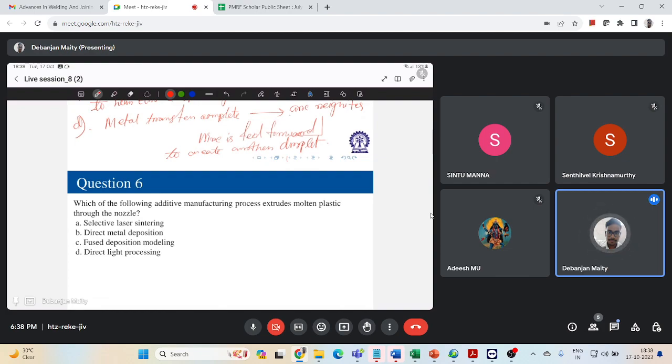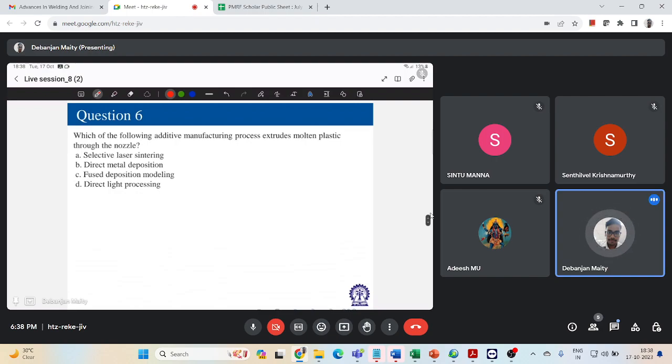Now, your CMT welding electrical signal consists of three phases. You have a peak current, where constant arc voltage corresponds with that high pulse current, and you'll have this ignition of the welding arc, which is very easy, and it forms those droplets. Then you have background current, which is a bit lower current level. In CMT, this background current prevents the globular transfer of the liquid droplet, and it continues until short circuiting occurs, right?